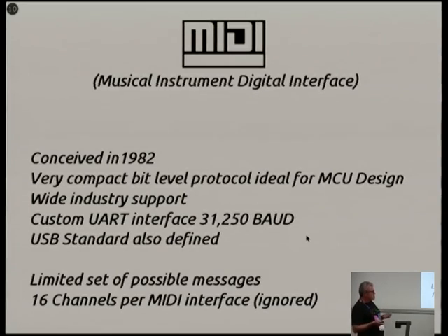Some of the limitations are it's only got 16 channels per message set, or per device. That generally is ignored by most devices. They listen on all of them anyway, because trying to set each device to its own channel, particularly in the software world, people thought was just too much of a pain. You start with one device and you're only ever going to use one, so I'll just listen on everything and make it easier. So the 16 channels don't really even exist as an expansion option. It's generally you've only got one kind of thing on each one.